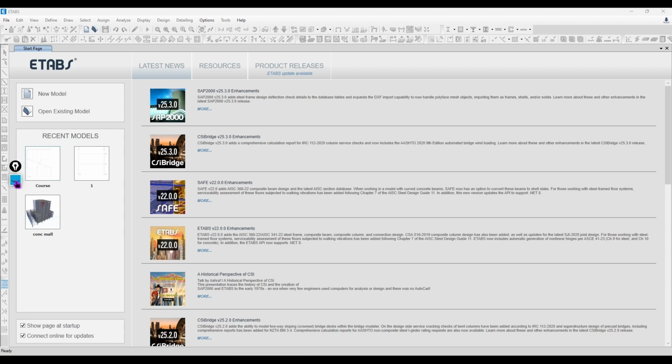First things first, what is software that does structural analysis? If you take a look here, usually this is what we have. Let's say this is a simple beam, this is a hinge, this is a roller, and you have some kind of load, like a distributed load of W in here. To calculate the reactions, it's simple. You can get sigma x, sigma y, and sigma moment, and everything is 0. This is because it's just a determinate structure.